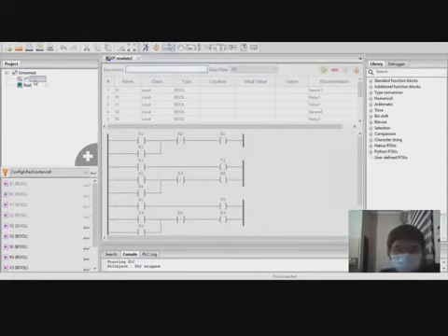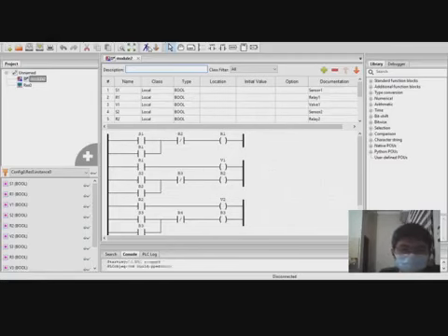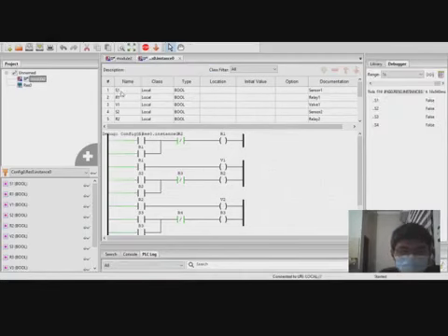We click module 2 here and we try to simulate. So the proximity sensor here is S1. When the first sensor detects the car, we will give a true value, then it will turn on relay 1. Relay 1 actuates and turns on valve 1.